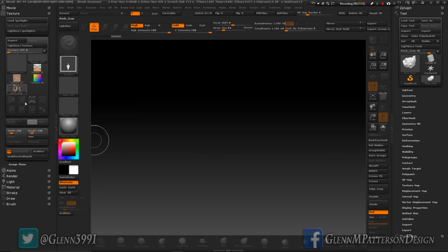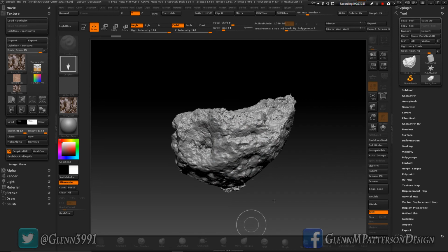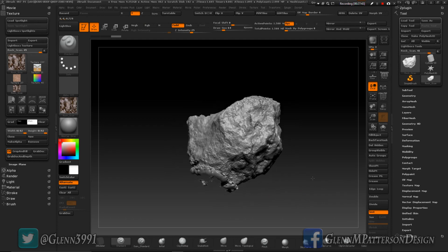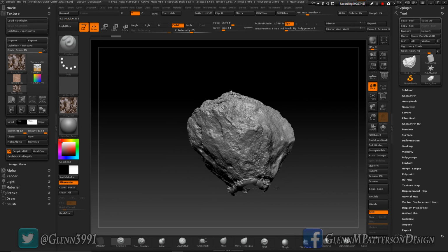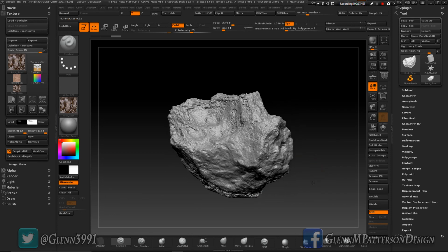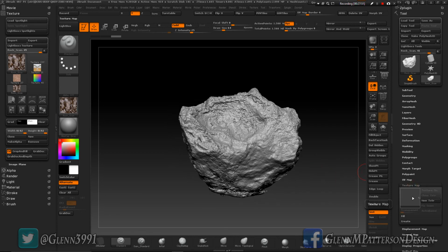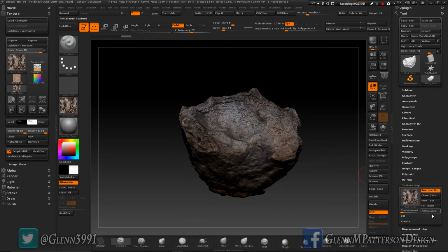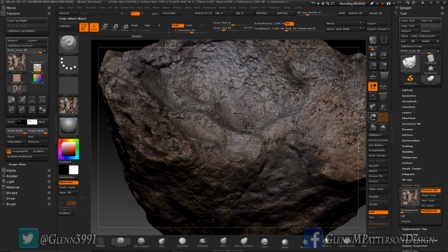So real quick with the rock scan on the texture, I need you to flip V, because all you ZBrush users out there know that for some reason ZBrush's texture system is upside down. So then we're going to do T for edit there and draw out our model. There it is, all nice and pretty, all 1.5 million active points. And go over to texture map. Now that we've flipped it, go to rock scan, load it up. We'll do anti-aliasing and zoom in here. We can check it out.